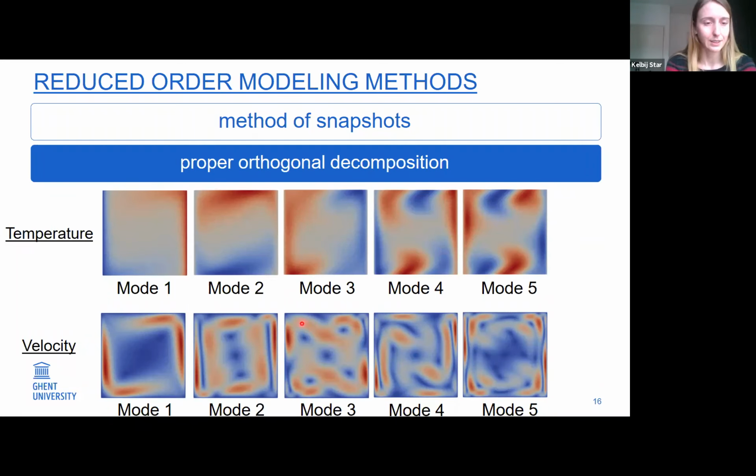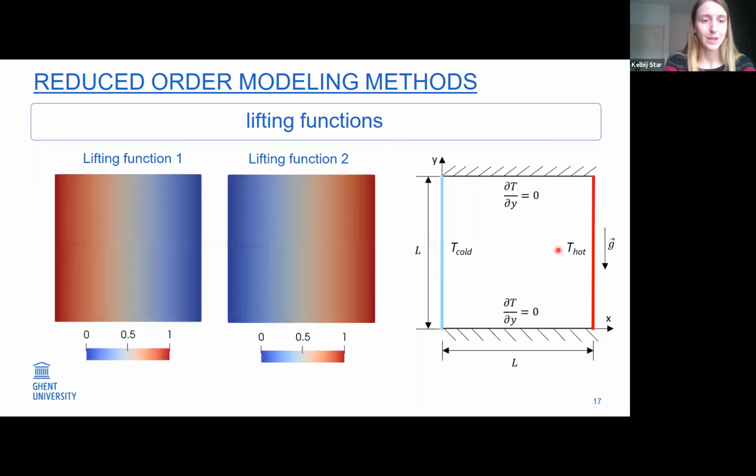So in the end, I'm actually using 7 modes, but I thought the pictures were getting too small at the moment. But anyway, like I said before, we need a method to impose the boundary conditions. So I use the lifting function method. I need to set up 2 lifting functions, and in this case, they're basically fields that I'm subtracting from all the snapshots that I collected.